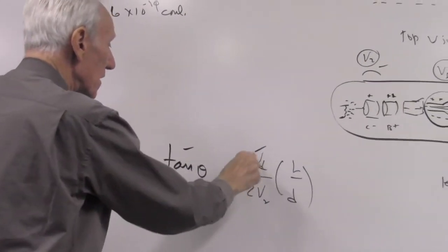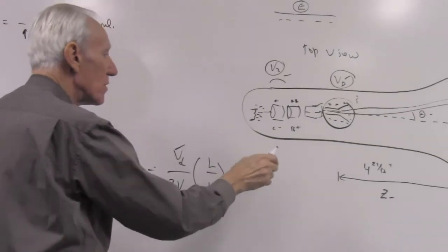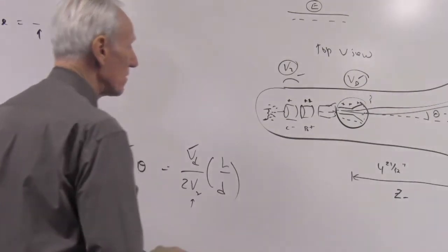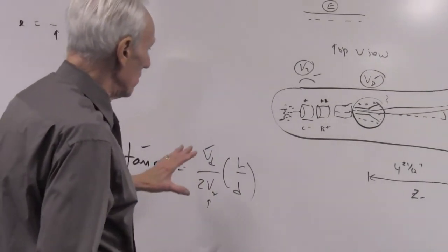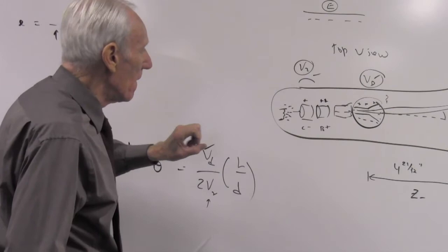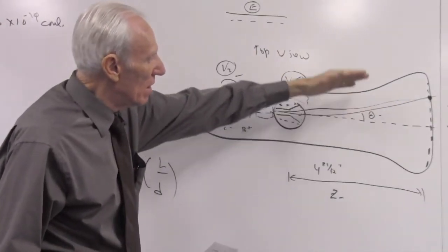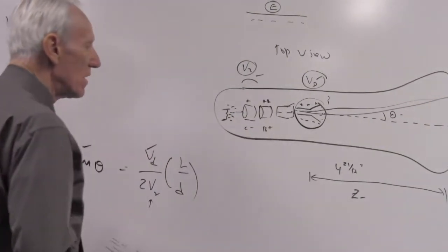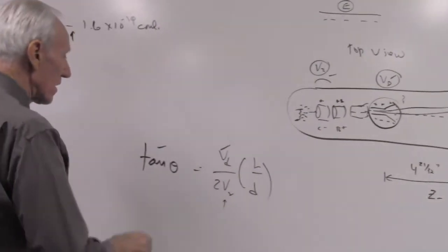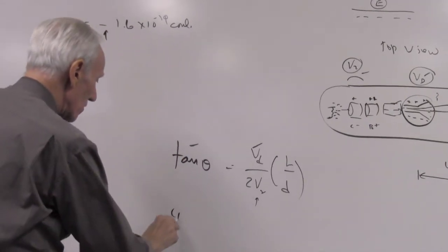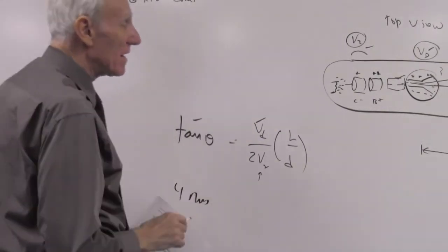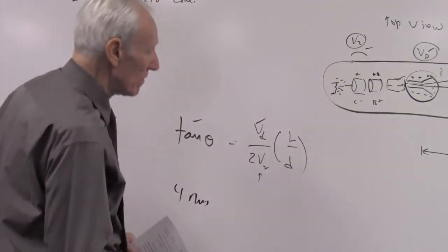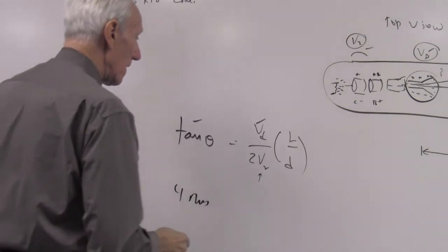We know the deflecting voltage that puts the dot on each one of those lines, and we know the accelerating voltage, which we set over here. So the process is to set the accelerating voltage and then move the dot across the screen from +1 inch to -1 inch, and then change the accelerating voltage and do it over again. So we're going to do 4 runs, and we're going to get 9 data points of where the dot is on the screen from 0 to +1 and then over to -1 in 1/4 inch increments.